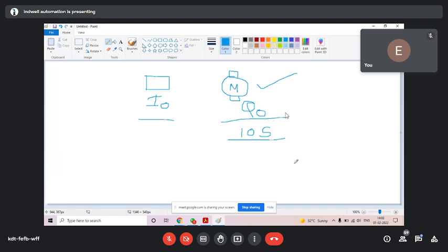Raj Shekhar, you have taken an Allen Bradley timer. But you have run this timer from the push button. From a push button, we cannot run the timer. Akshay Patil, you have taken Q. No, no, no. You have run this from the push button. From a push button, we cannot run a timer. Try again. Sahib, it is not correct yet.